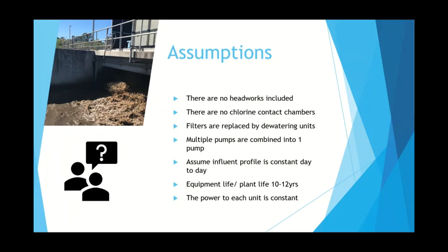Multiple pumps are combined into one pump with a power representing the sum of the individual pumps. It is assumed that the influent profile is constant day to day, and for costing purposes, it is assumed that the plant life is 10 to 12 years. As well as, with the exception of the aeration basins, it is assumed that power to each unit is constant.